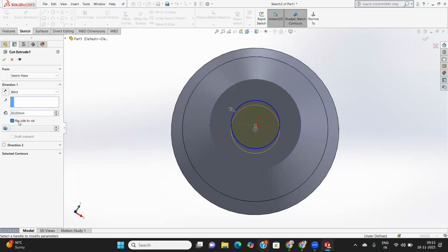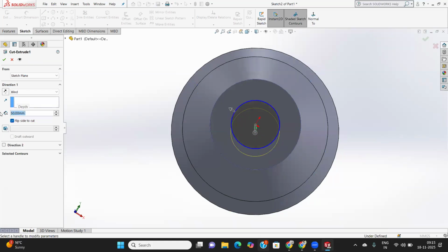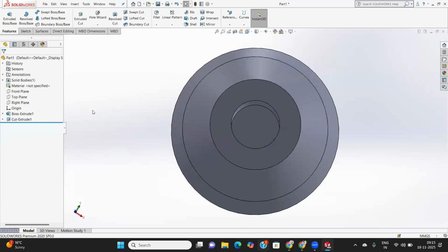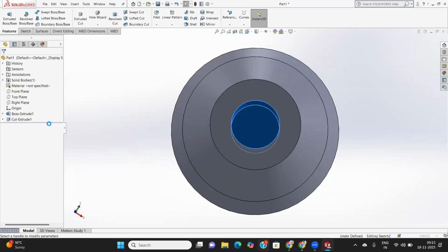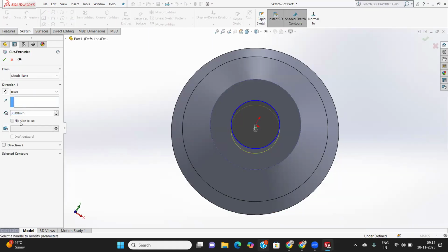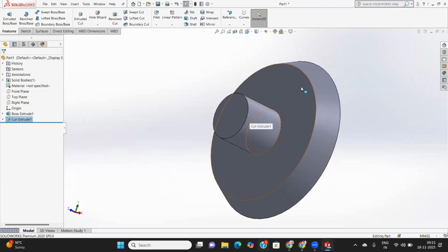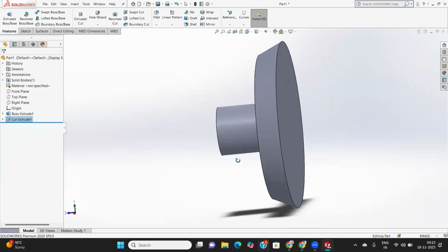If you click this flip side cut option, you can write 50 here, or whatever value, and then click OK. Now it's there. I think this is the total length cut here. One second. I did it the wrong way. This is your flip side cut right there, and then click on this portion. Once you select it, the remaining side portion stays and the other side portion will be removed.